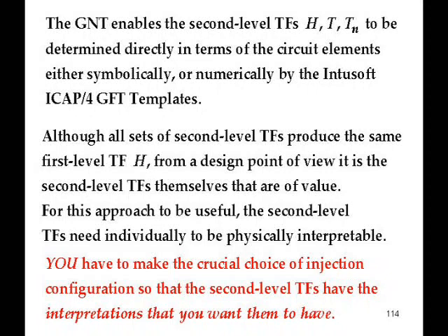They all produce the same first level transfer function H, but in fact, you don't really want to plug them into the formula to find the H. It's the second level transfer functions themselves that are the useful things to know for design purposes. That's why you have to choose an injection configuration so you can interpret what they mean. Because they're the things you're going to design individually to make the H come out to meet the specifications. So you have to make the crucial choice of injection configuration.